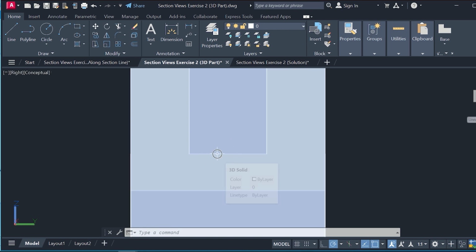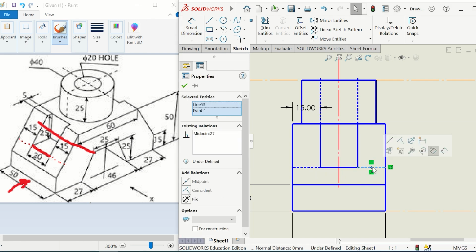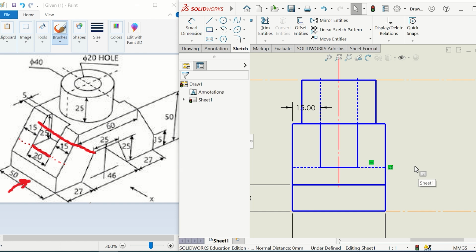By chance, there's a visible edge here overlapping it from this point to this point. So that hidden line, which starts here and actually ends here, is overlapped with the visible line, but only partially from here till here. And this is how it appears. As I told you, this is one continuous line all the way till here, that's overlapped by a visible line, and therefore it only appears hidden here and here. And that would conclude the right side view.